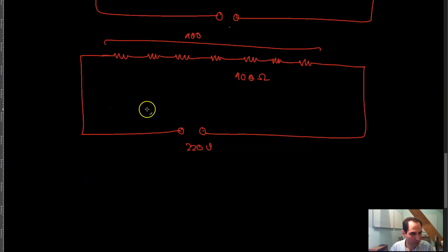And now you might have seen that these lamps, if one of them is damaged, then the whole string goes out. And then usually what people do is that you have to check one by one which one is faulty, and then take it out and replace it with a new one, and then again the whole thing starts lighting up, right? Which means that, for example, if this lamp over here goes out, that means that over here you will have basically infinite resistance, meaning that it's an open resistance, completely open, and so the circuit is simply open, and so no current goes through the circuit, meaning that none of these lamps will light up.